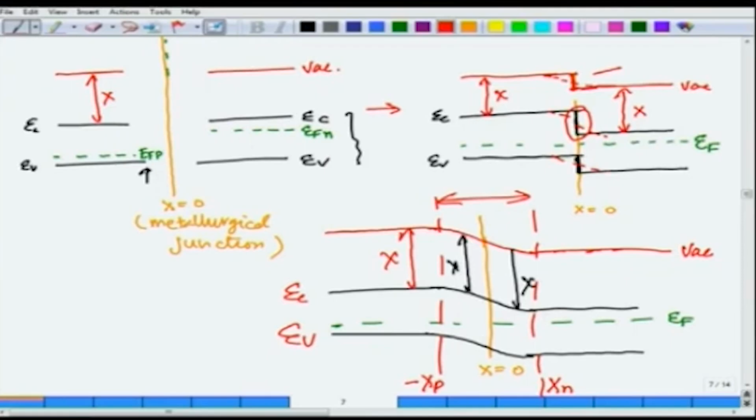So this is your E versus R diagram. This is E and this axis is position R, and this becomes a combined band diagram of two materials together. One point you have to remember: if I take this as the zero reference of energy, then I have changed this end of the semiconductor by this much amount. This is typically called QV.